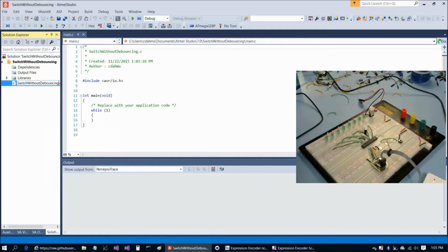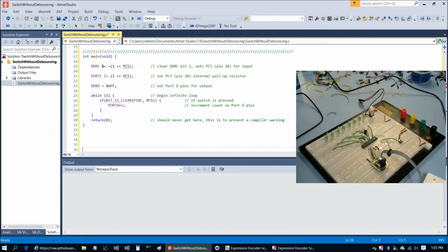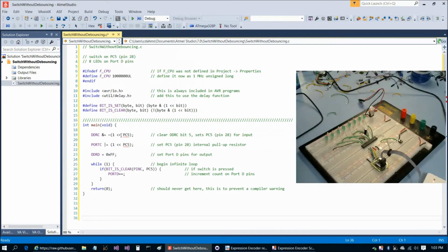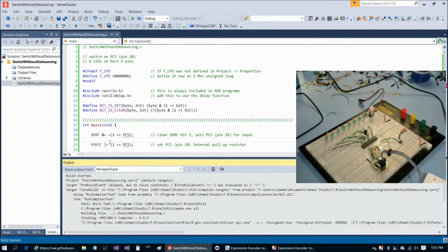Then we'll rename main.c, and we'll copy and paste in the code after turning off code folding. That's Control M, Control P to turn off code folding. And there's our program, and once we bring up that io.h file, then these red underlines will disappear. But first let's go ahead and run the program.